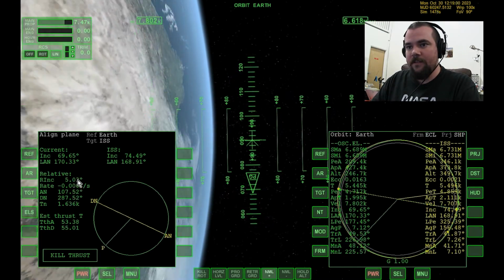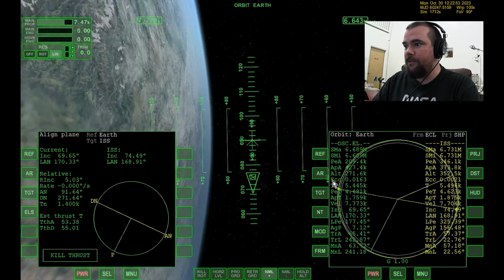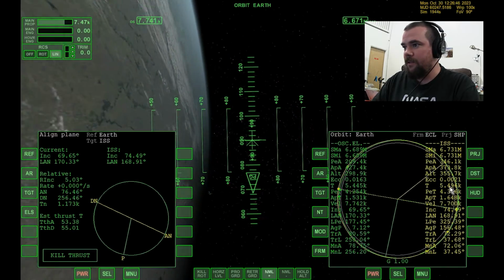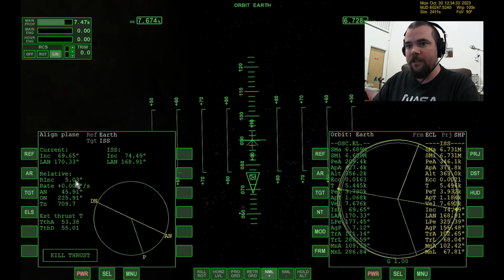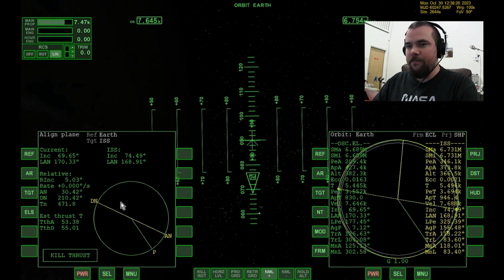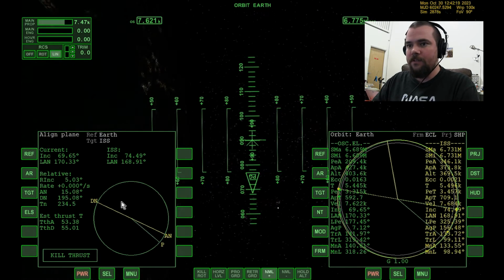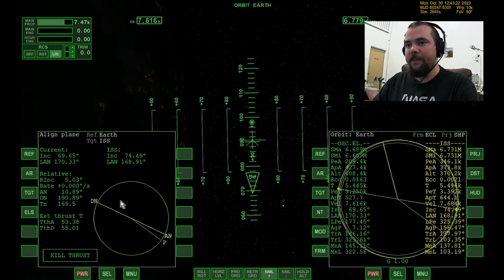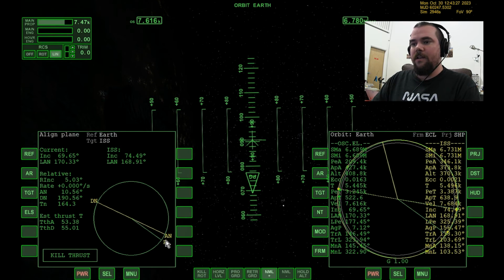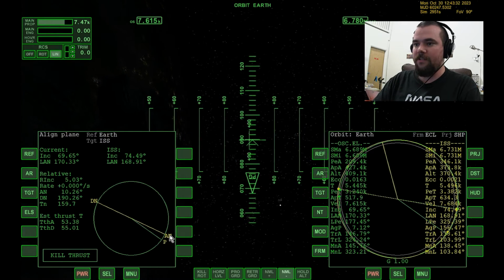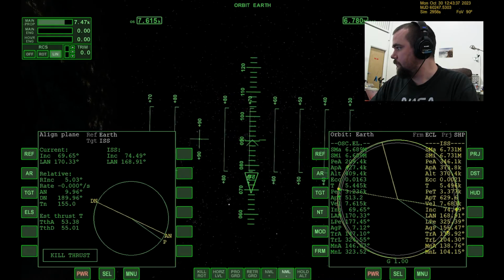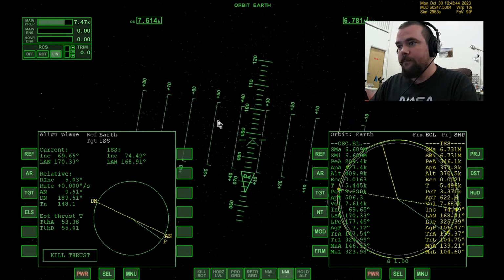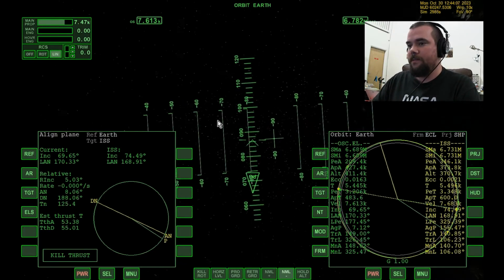All right, so let's see if I can get this last. I'm down to 5 degrees, and you notice over here, the ISS already looks mostly like a circle here. But we're still about 5 degrees off. And you can get this down to 0.00, which basically means less than 0.005 because of rounding. Okay. And so this time I'm approaching the ascending node, which means I need to point myself in the anti-normal direction. Go ahead and do that.